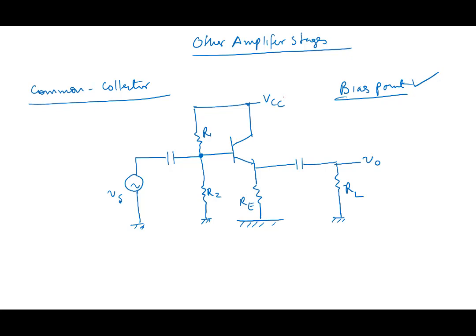As an example, let's say, suppose this is 6 volt, and we want output at this point here. Let's say I design it in such a way that, for example, this is 1 kilo ohm, and we design it such that the DC voltage here is 3 volt. So we are talking about emitter current or collector current, ICQ, of 3 milliamperes.